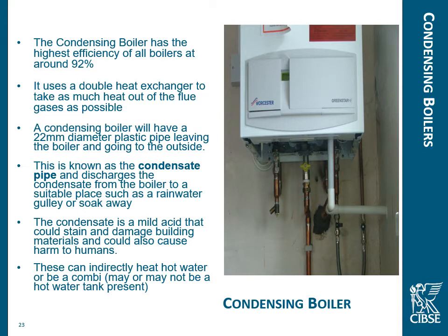So we can see the plastic pipe leaving the bottom of the boiler there, and that will always be the condensate pipe. If we put the condensate into a copper pipe or an aluminium pipe or a steel pipe, it would quite quickly corrode away at the pipe.